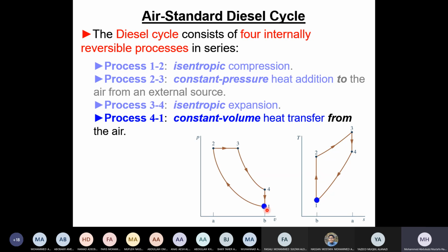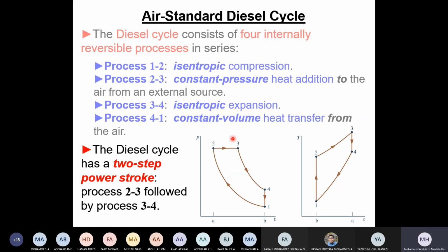The next step is to make the cycle analysis. What does that involve? Calculate W compression, calculate the heat addition, calculate W expansion, calculate Q_L, then get W net, and then get the efficiency. It is the same procedure. The only thing that differs is this process. So now let us go to the cycle analysis.